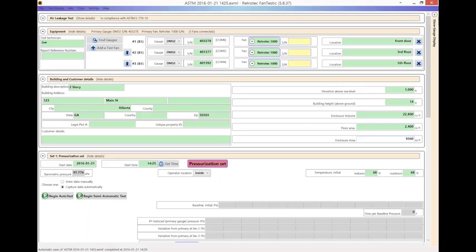One of the things I have slides for, but I thought I'd talk about the software first, is that you can do air changes per hour, which is very common, and many of the folks out there are used to doing air changes per hour when they do a blower door test. You can also do more of a commercial style, which is surface area, which is all 6 sides of the box, and how much leakage I have per square foot. There are different ways that it can do it, and this can do all of them together, but it needs some of the information that's on there.